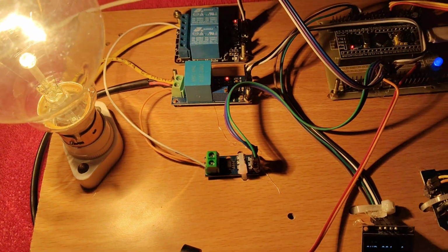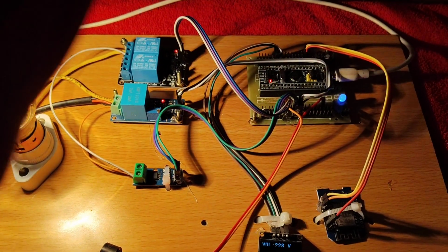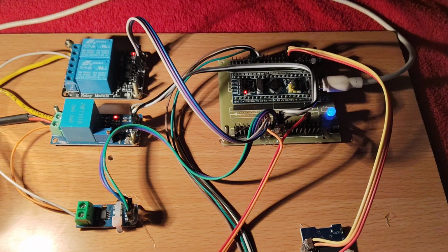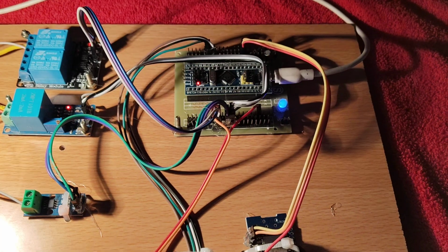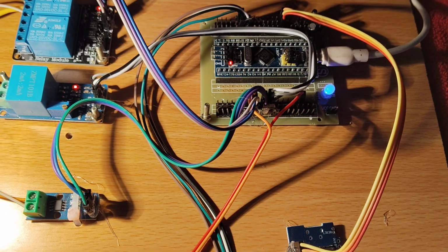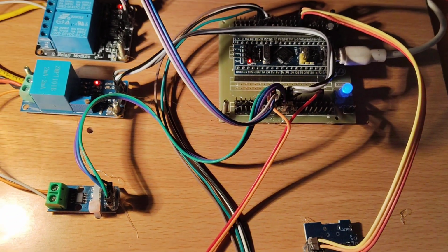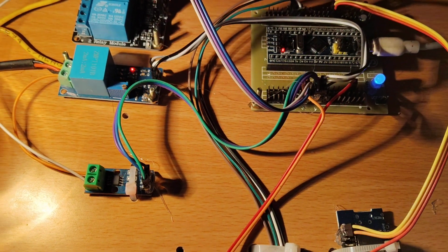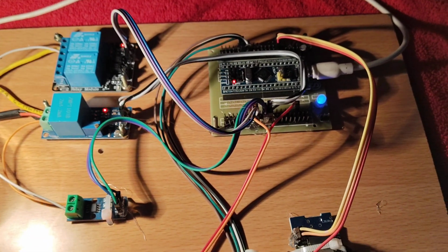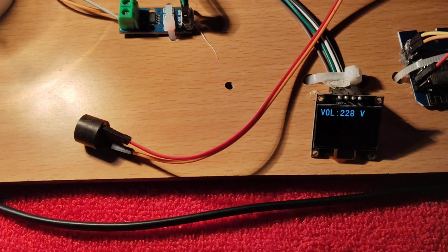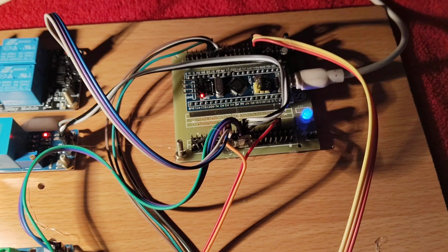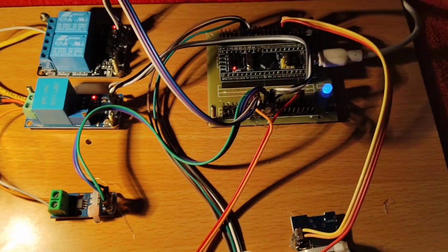So this is our project, and as I said, we have used UART serial communication here. To transmit the signal, we have connected PA9 on the STM32 microcontroller, and to receive the data, we have connected the PA10 pin. The voltage and current sensor pins are connected to analog pins. The OLED display is connected to I2C1, with the clock pin connected to port B 6th pin and the data pin connected to port B 7th pin.